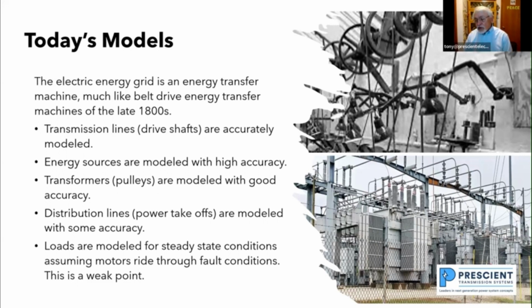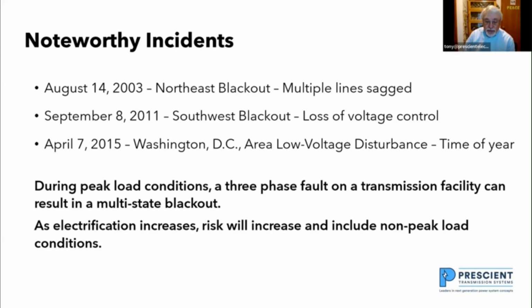And then we get to loads. So loads are modeled for steady state conditions, and we make the assumptions that motors ride through fault conditions. And this is the weak point in the models that we're using.